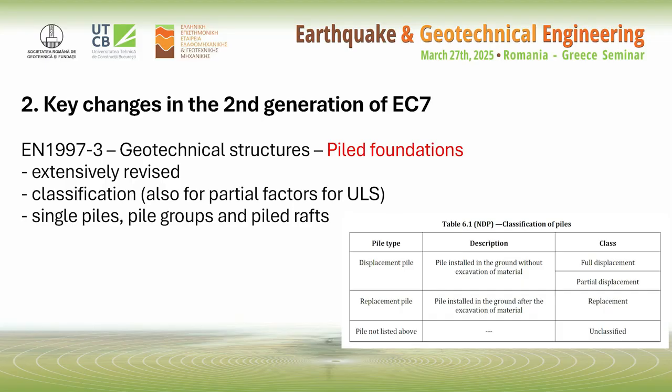Piled foundations, and here we have to talk a little bit more because this clause was extensively revised. We are starting with the classification of piles into displacement, replacement, and some other type of piles. And this will influence the partial factors to be applied to ULS, so this will depend on the classification that we make from the very beginning. This clause will apply to single piles as until now, but also to pile groups and piled rafts.